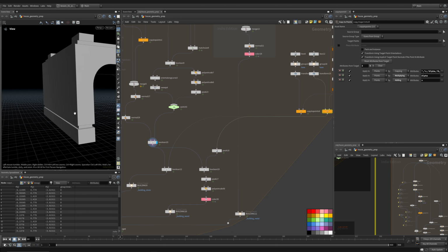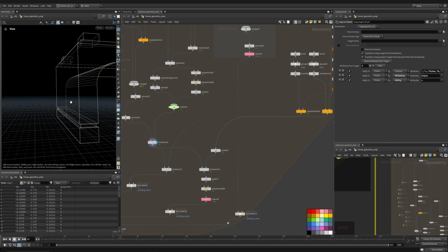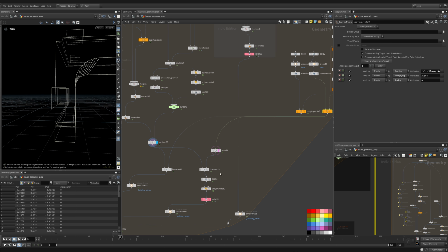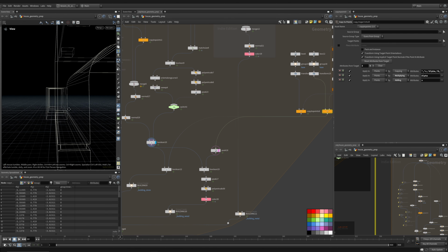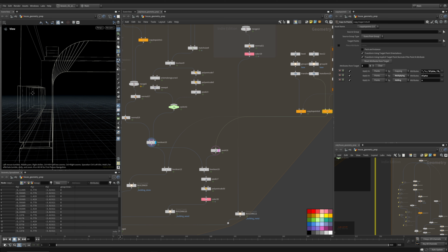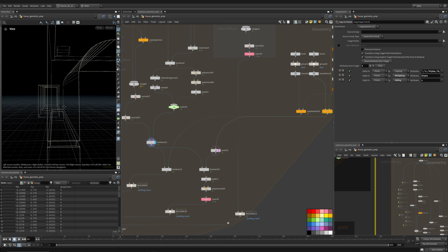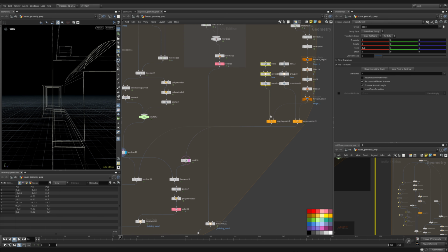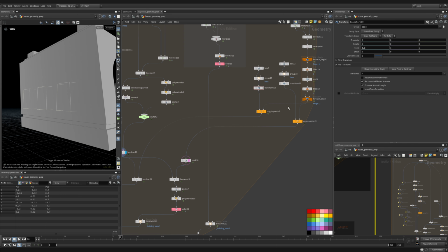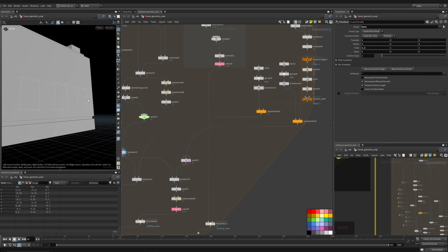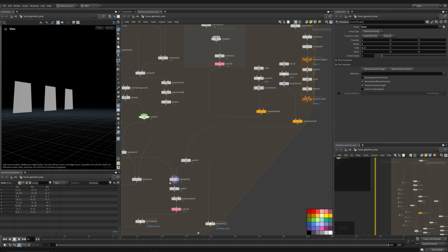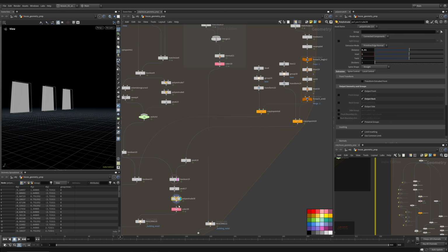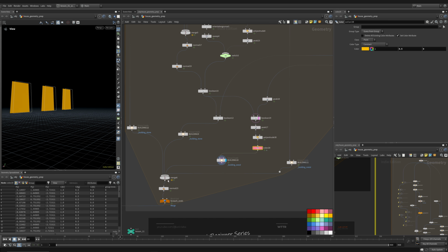and then when I connect this to here, that will give me this Boolean cut again. So this Boolean cut is giving me one face because it's extending and it's only cutting through one side of this wall. You see, it doesn't cut through the second side. And I split that up, and I could have fixed it a few different ways, but this was a fine way to split it up because it is easy to read and it was easy to set up. And then here I peek it. And we'll merge and see what happens.